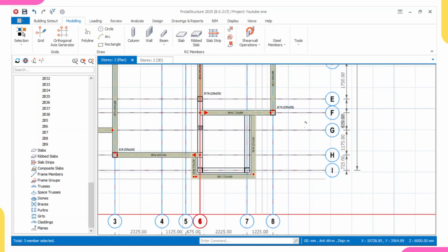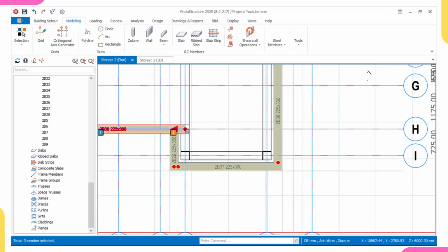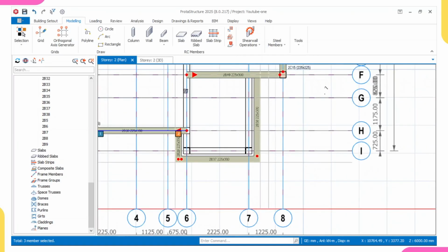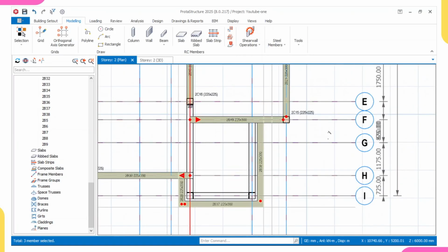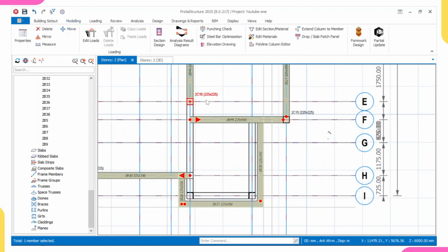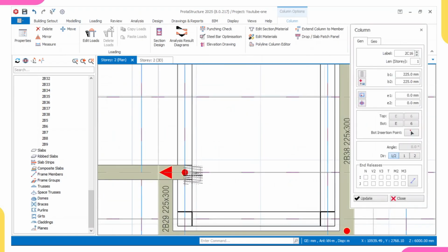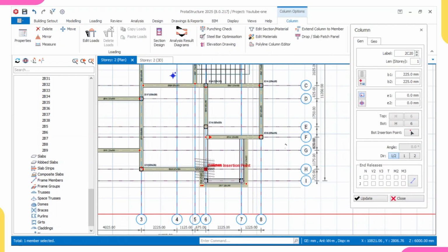But I don't really want that. So for that, I want to introduce a column here, to minimize, because if I introduce a column here, that means this beam now will no longer be a cantilever. So what I'll do now, I'll right click, in which I told you structural design is totally dependent on the engineer. So I'll place a column here. So if you say I've placed a column here, that cantilever sign have gone.